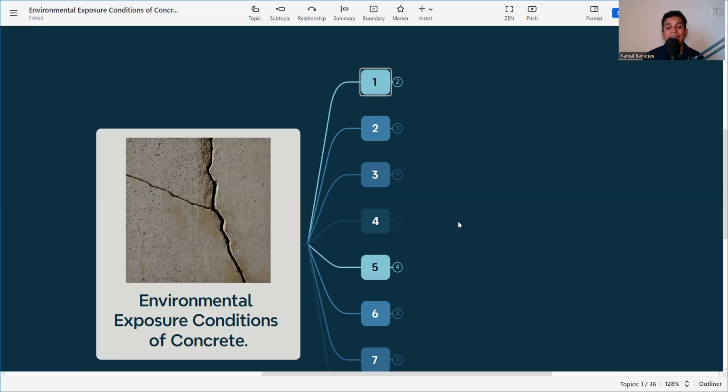According to the area where my concrete or structure is placed, there are different conditions. An area that is not too dry or too rainy, compared to an area where there is too much rain throughout the year, the same concrete cannot withstand. So we need to do the concrete as per our exposure condition.